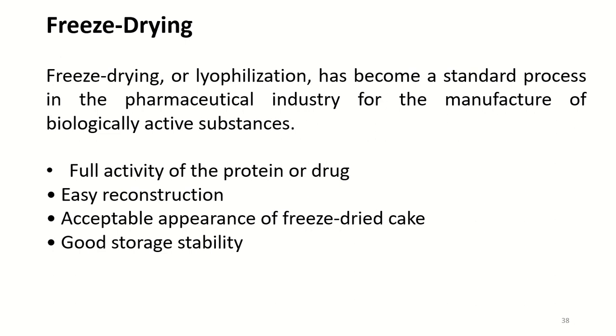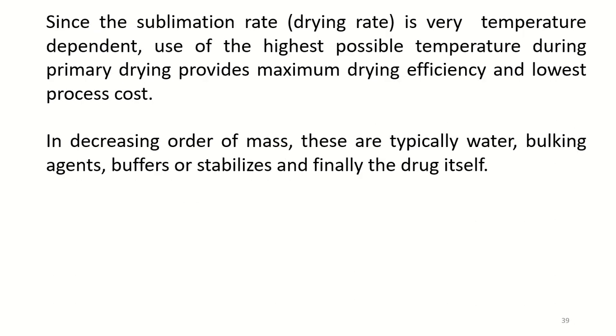The process of freeze drying relies on the vapor pressure of ice. Even at temperatures as low as minus 50 degrees Celsius, ice sublimes and leaves a very porous, low density cake containing the stabilized drug.